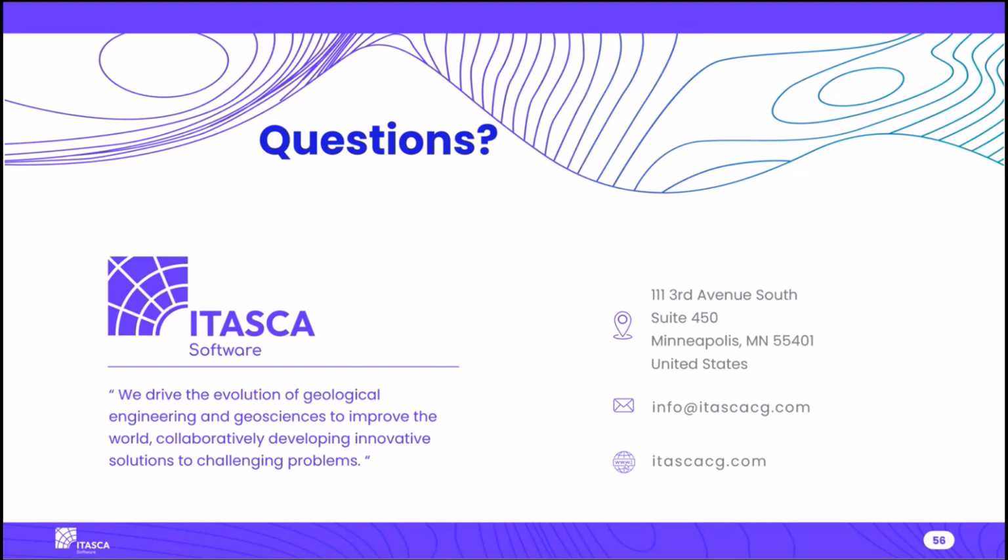Oh, sorry, we just got a last question. In the comparison between Rayleigh, Maxwell, and deep soil damping, we observed that Rayleigh damping overdamps on high frequencies. In the formulation, the damping ratio is practically constant over an intermediate range of frequencies and has higher values for lower and higher frequencies.